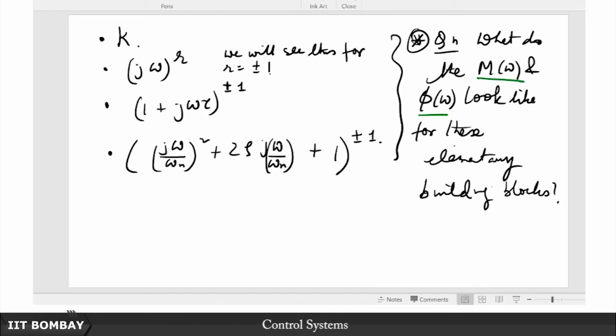Independent of root locus, Bode plot is supposed to allow us to design lag lead compensators just like we did using root locus, okay, independent. So this time domain control design like root locus and these frequency domain control schemes like Bode plots are supposed to run independent of one another and they are supposed to give us equally good performances, okay. Similarly, by frequency domain characteristics, we should also be able to specify performance metrics.